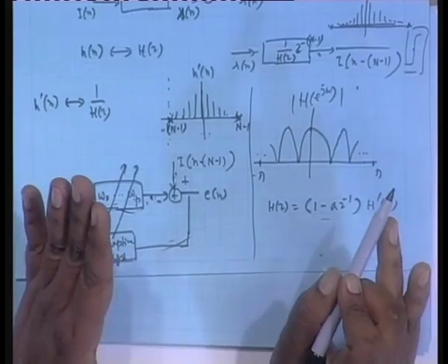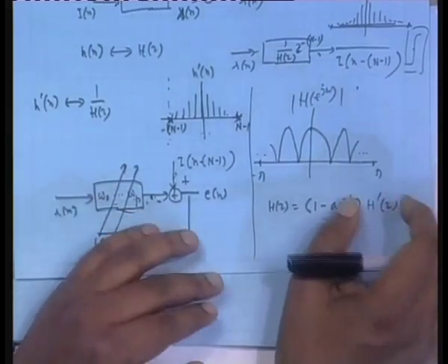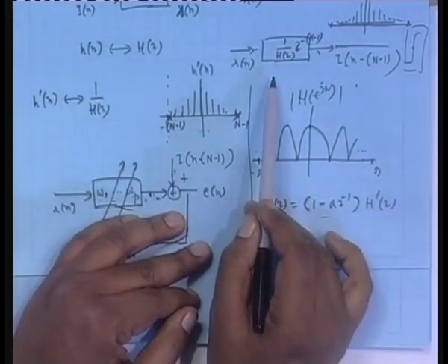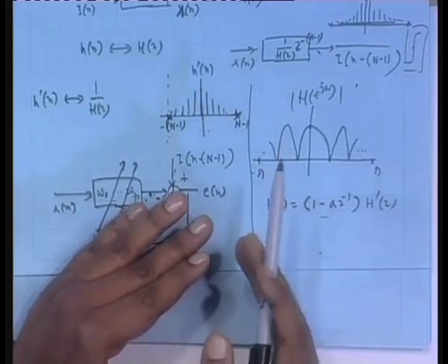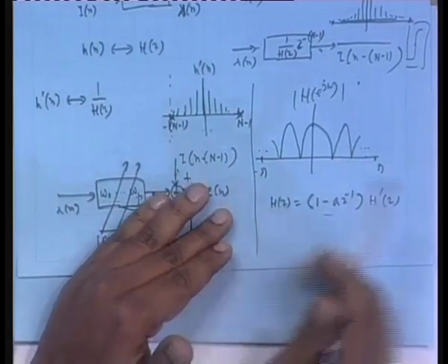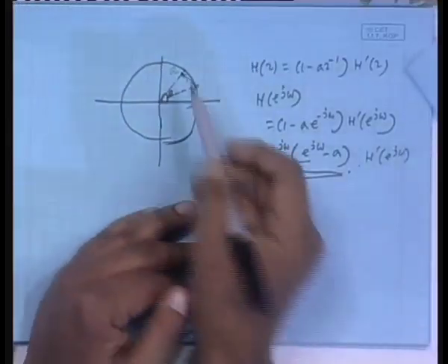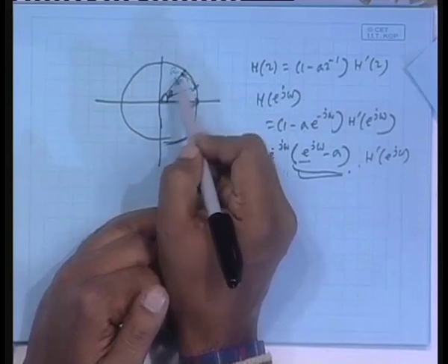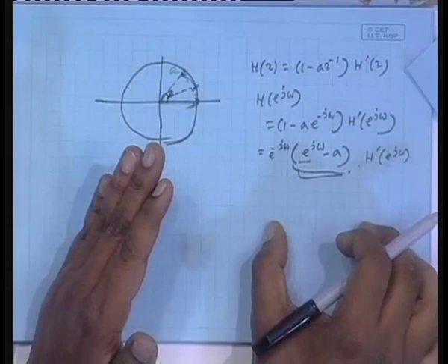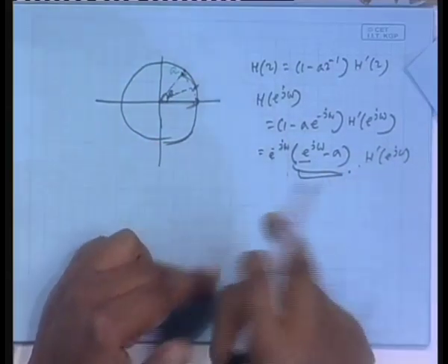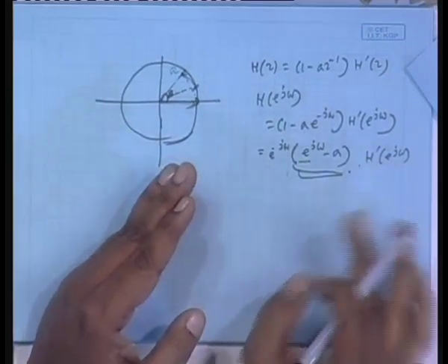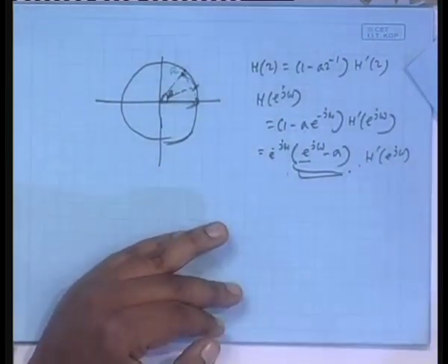Okay. Now, if that be the case, I was discussing H(z). So, this equalizer is 1 by H(z). That means there will be spectral peaks, zeros became poles, isn't it? Earlier it was just the phasor, the difference phasor magnitude, that is close to 0. So, overall magnitude of the response was 0 or very close to 0, but now it is not H(z), it is 1 by H(z). So, it is like 1 by 0 or 1 by something very close to 0. So, that will shoot up to infinity, it is a peak, isn't it?